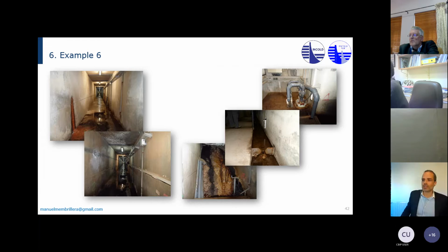This is what the dam looks like on the inside. You can see the galleries with a lot of seepage. These conglomerates, the cement from the conglomerates, watch out for this. You can see this being dissolved and being dragged into the dam. A lot of moisture all over the place. So the monitoring sensors, seepage weirs, and pendulums, we have lots of issues with moisture.